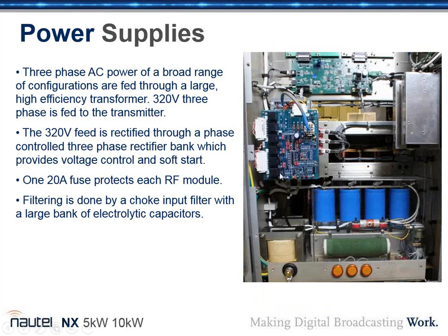You've got the phase regulator that we looked at here, and then we've got the filter bank here, and we have the choke input filter chokes there, and that's for discharging the capacitor so that if you open the front and back of the transmitter door quickly, you don't get zapped. That's right. There's 400 volts there, so you don't want to touch that.